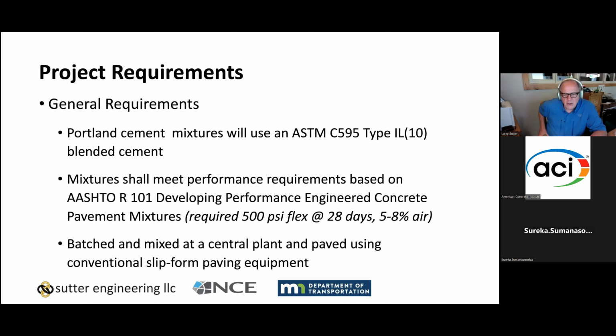The real kicker was that we said all these various mixtures had to be batched and mixed at a central batch plant, and they had to be paved using conventional slip form paving equipment. We had some manufacturers that wanted to use volumetric mixers on a job site. Some wanted to form rather than slip form pave, and we just said no, we're going to do it the way we would do a pavement. This is going to be a real world test. Everything had to meet those requirements, and that did eliminate some materials from the matrix.